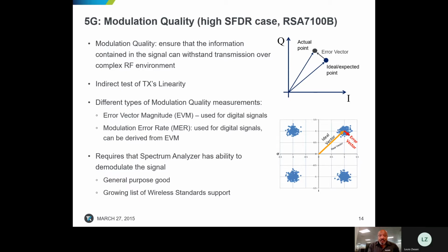So if there is distortion, if that decision region becomes blurred with the other one, it is due to some incident in the transmitter or some item that needs to be investigated. In short, the equipment needs to be better than the environment in which you're transmitting in, to make a determination that indeed the unit under test can perform well in the environment that it's going to be subjected to.